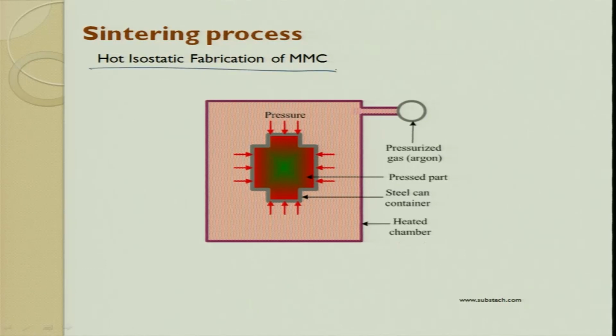we try to do hot isostatic pressing. In hot isostatic pressing, the powder along with the mixture is put inside a die. This die can be a flexible die. So, we put it inside and then we apply hot air or very high pressure around it. Now there is proper consolidation happening and you get the required quality output. So, proper consolidation is very important.